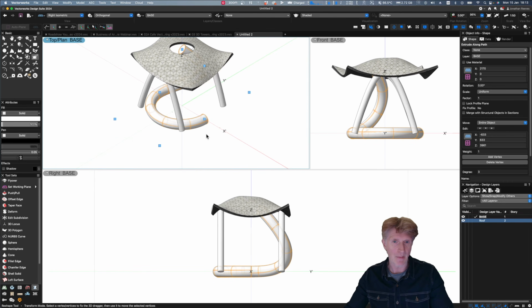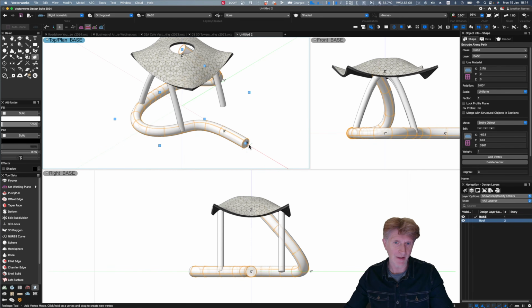Now let's also get my reshape tool, and I want to show you that if I click on the plus mode, I can add in additional vertices as well. So these can be quite hard to control, but just be careful of the direction you're moving them. So you might want to lock various axes. So I'm going to turn the x-axis on. Now when I click my plus, you'll notice that it locks onto that and it generates in the x direction. If I go onto the y direction now, when I click plus, it starts to turn upwards.